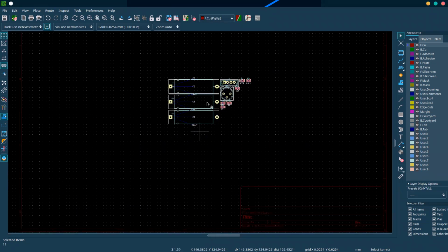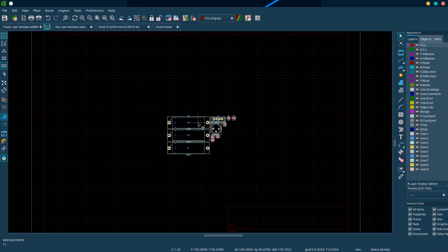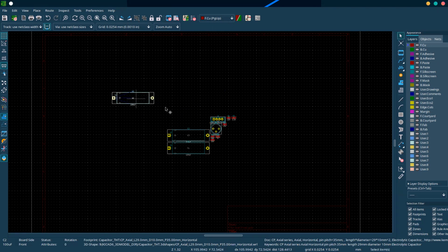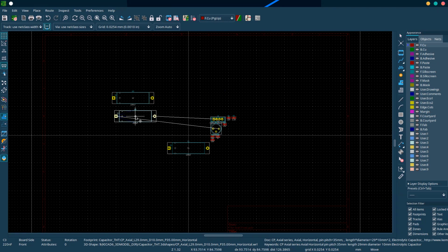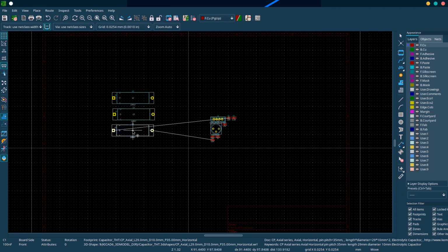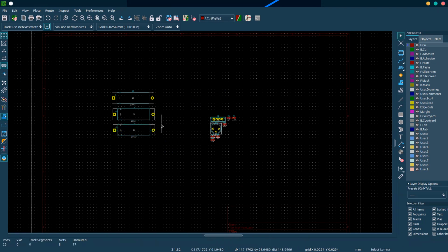So now that we have our components, it's kind of the same deal as always. You can hover over a component, you can rotate it, and this is basically how you lay out a PCB. So remember, the location of these things is the actual layout of your PCB. Like, this is what it will look like. So in the schematic, it didn't really matter if your wires were all over the place. Here, you actually want things to look good.